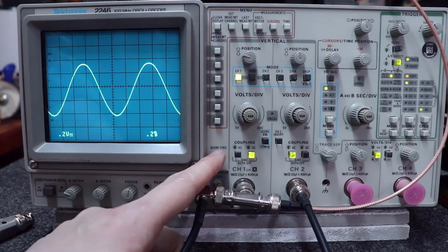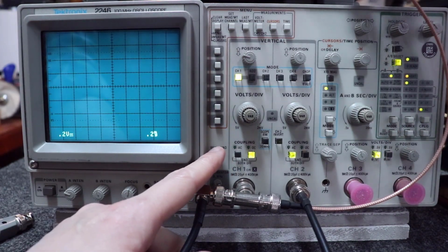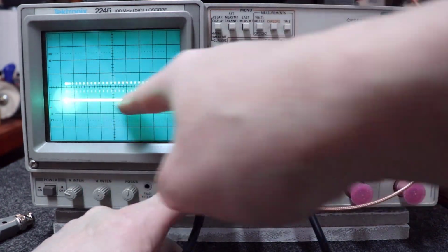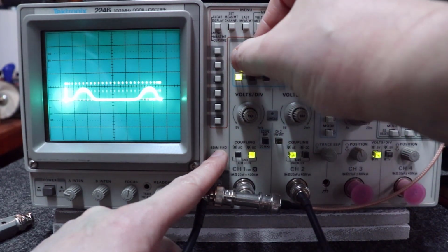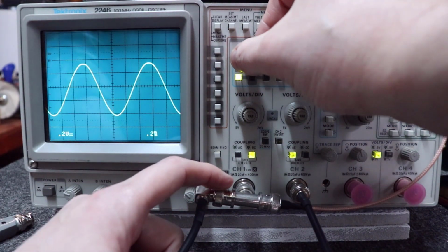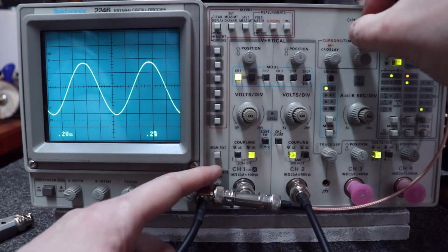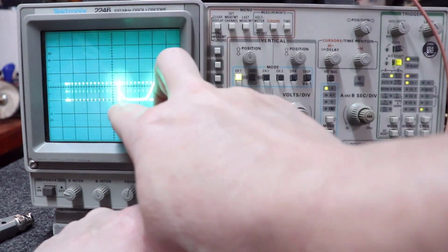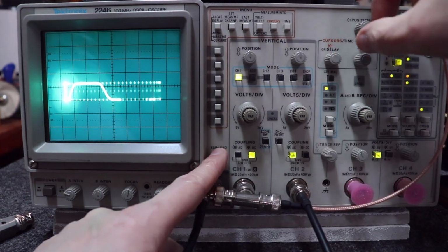Now, what if it was out the bottom? Well, let me take it down this way with some negative DC offset. There we go. This line down here is brighter than that line. It's showing you it's off the bottom. You would know to turn your signal upwards to get it where you need it. Let's say it's off the screen to the right too far. You can see here, it'll give you an indicator that it's scrolled off to the right, or an indicator it's scrolled off to the left.